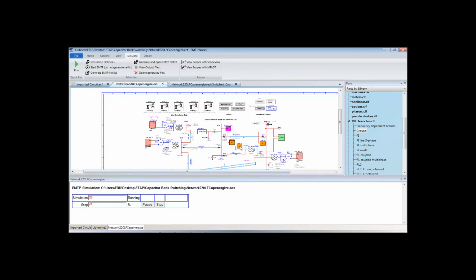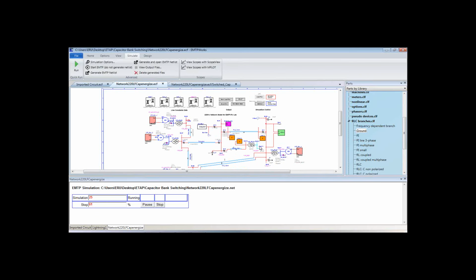By the way, we can use the same statistical analysis for a lot of different parameters, for instance, the instant of transformer energization or cable energization. This allows you to quickly have a look at the worst of the voltages that can happen in your systems.